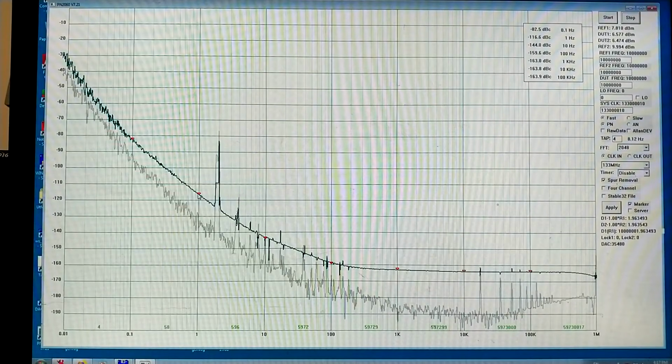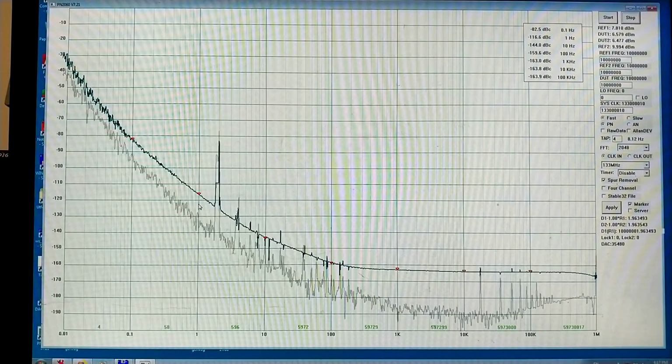And I know that a single crystal in a good oscillator with very low amplifier noise could give minus 123 dBc per Hertz. And with 4 crystals, I might hope for 6 decibels lower crystal noise, would be minus 129 down here.